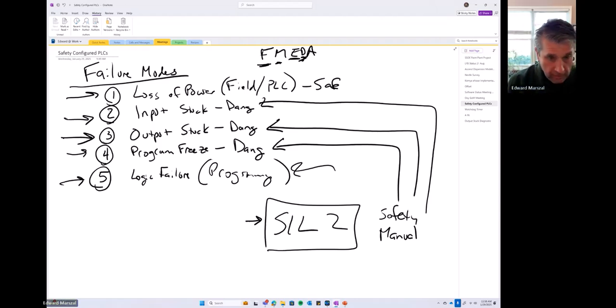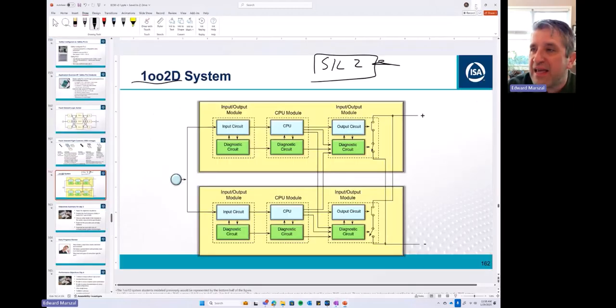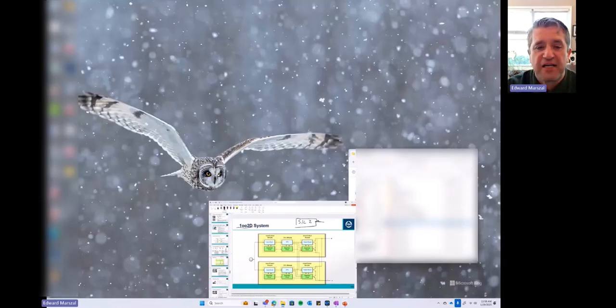Neither 61511 nor 61508-1 mention the term certified devices. Correct. Does 61508 part 2 or 3 use the term certified? If not, what is the correct terminology recommended by the code? No, it does not ever say certified.